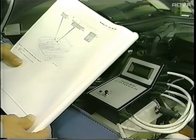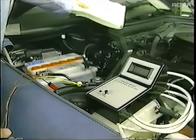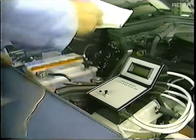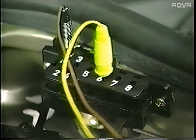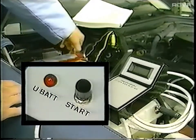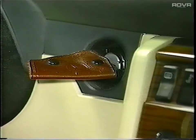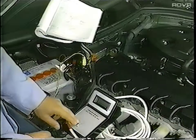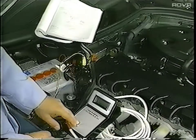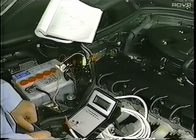The test procedure is facilitated with the use of the impulse counter, which eliminates the need for counting blinks. The counter leads are connected to the test plug as explained in the introduction manual. When the power input is connected, the LED will illuminate to indicate that the voltage supply is correct and the tester is functioning. With the ignition switched on, press the start button for no less than 2 and no more than 4 seconds. A number from 1 to 10 will appear.